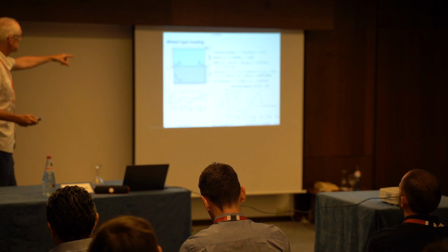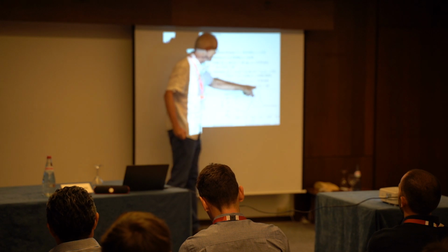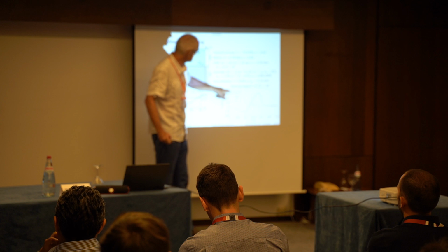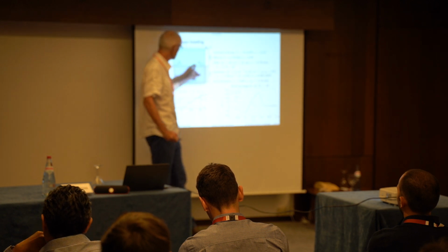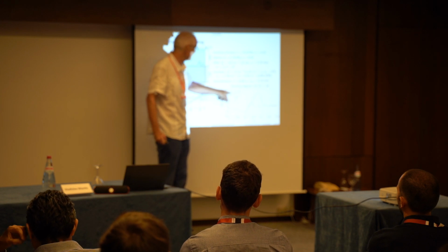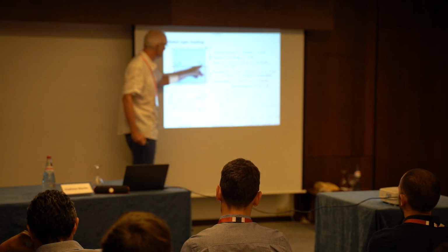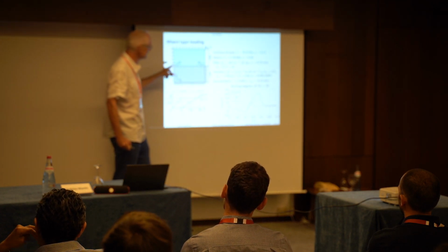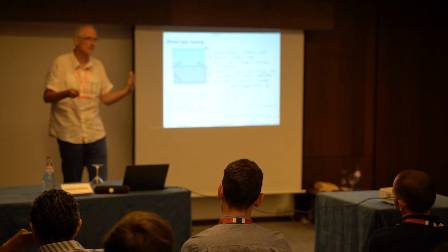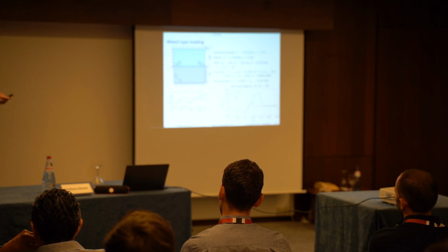What about the presence of the interface? Again, here we set the GCs in the material to a flat value, and we can observe how the behavior depends on the adjustment of the GC along the interface. Again, small value, large value. Here we will see that the crack appears on the interface. For this curve, the crack is in fact the same as if there were no interface, because the interface was not cracked.